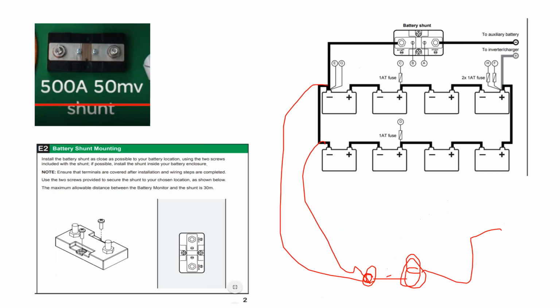So we had to sit down and say, well, if we paralleled them, we already have the cable here, and if we just did it to 1, then we're only measuring half the current. And if we have it in line with 1 circuit, not the other, that changes the resistance, and we don't want that either. And then we said, well, let's just double lug it. Of course, that's what we're supposed to be doing.